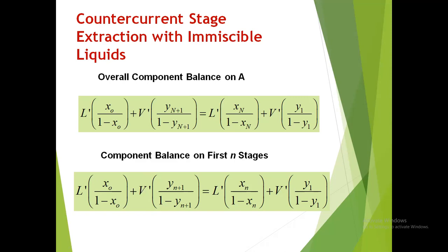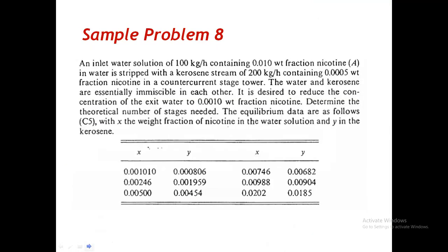Or if your solvent contains your solute, you take away the solute from that particular solvent, that would be now your V prime. The V prime that you have in here and the V prime that you have in here are the same. The L prime and the L prime that you have here is the same. If you have an aqueous feed, your L prime is just the water content of your feed. If you have a pure solvent, your V prime is the volumetric flow rate that is given in the problem, as is, because your solvent does not contain the solute. So just like gas absorption, you have three formulas to use.